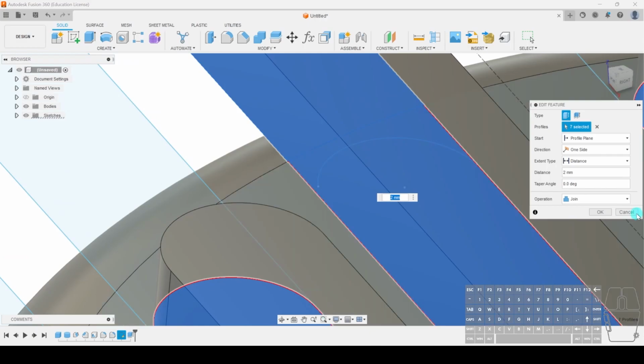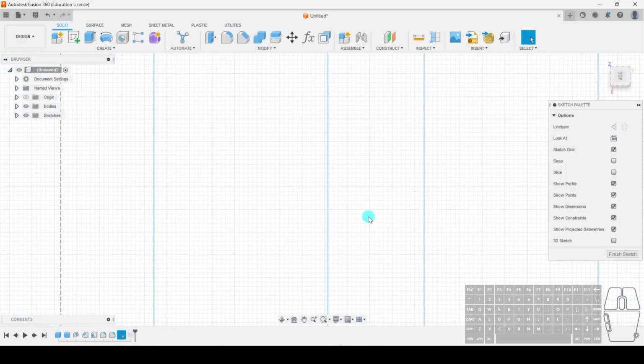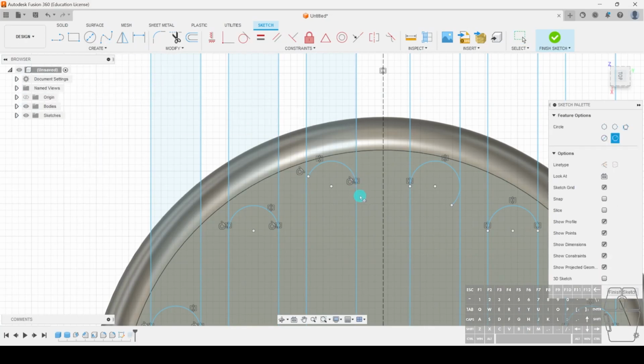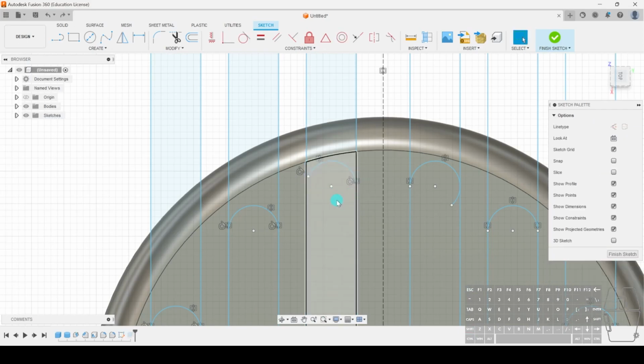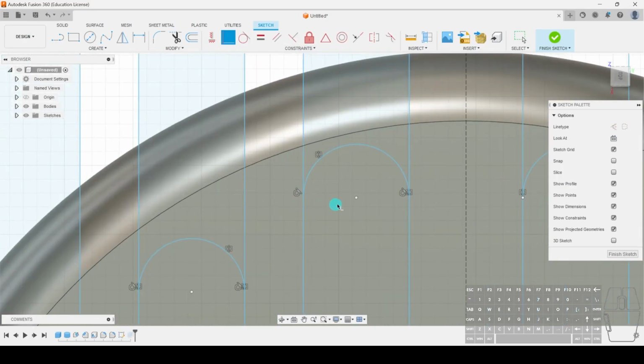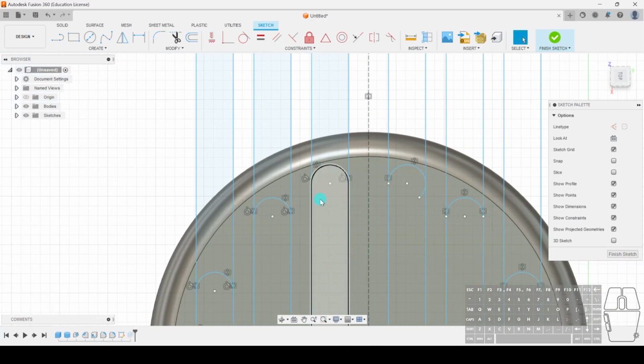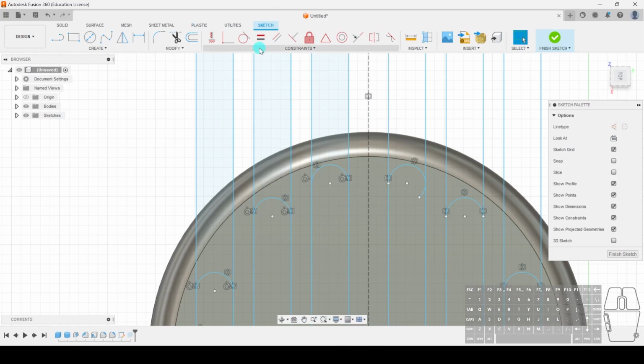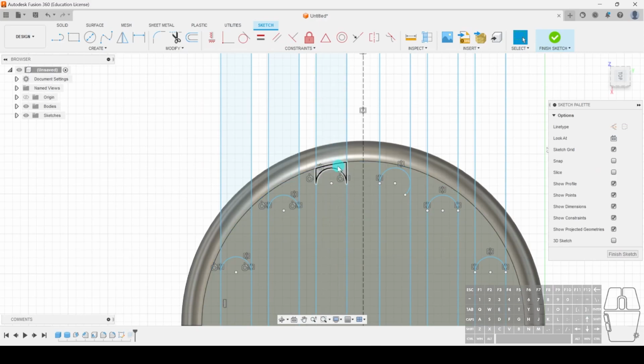So if that happens, the best course is just to redo with the 2 tangent circle. Select the line, place it wherever. But you can also select coincident, which basically just means connect this point to this line. And now it's coincident. And you can see my profile has been repaired, right? So again, play around with the constraints, really understand what they do. And if your profiles do not match up, it's probably because your lines are not connecting.